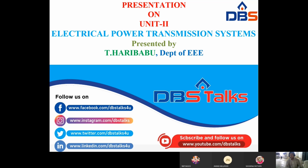And ABCD parameters. ABCD parameters describe the voltage and current relations of the two-port network. The input voltage and input current must be expressed in terms of output voltage and output current. Vs is equal to A VR plus B IR.